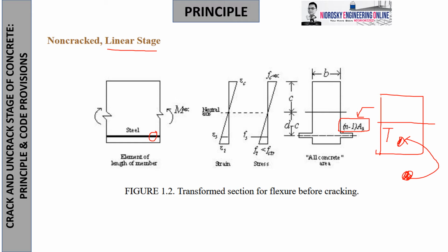So meaning, small participation of the steel rebar, as you will experience. So in calculating, it will be of small participation. Therefore, the code allows us to neglect the effect of the steel bar whenever we are trying to understand the non-crack stage. I'll try to point out and stress those sections in our code. This is for the non-crack.